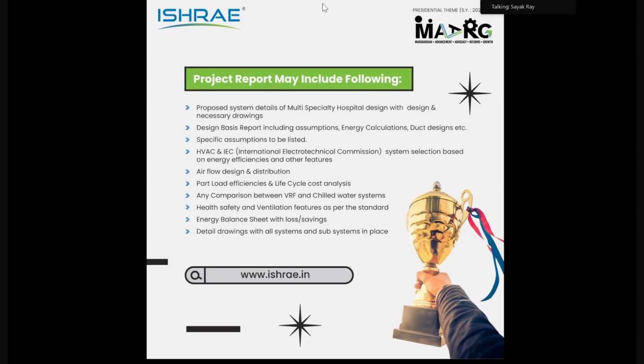To calculate the heat load, you need to first know what heat load is, what the factors influencing it are, and how to calculate it. Once you go there, you will find there are many different things you have to choose, such as what you would put in each of the rooms, how to separate the floors into zones, what the U values are for the walls and everything, and what the wattage factors are for all the equipment you will use.